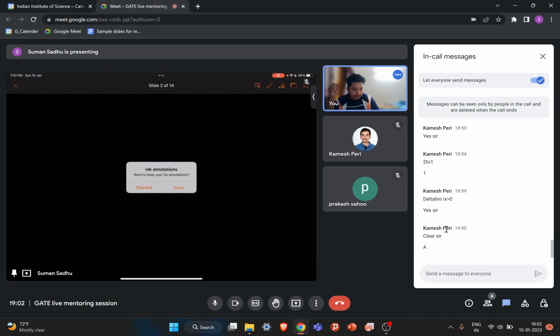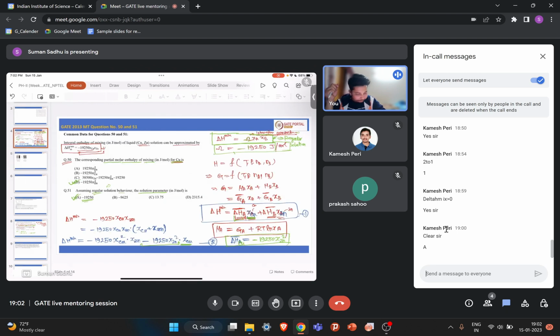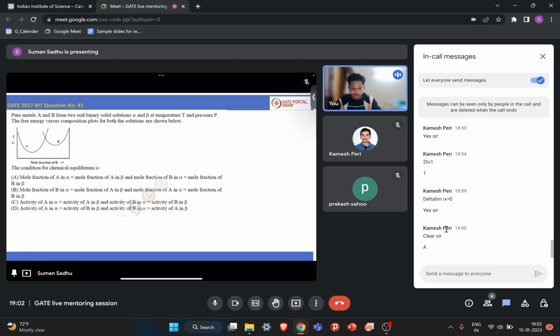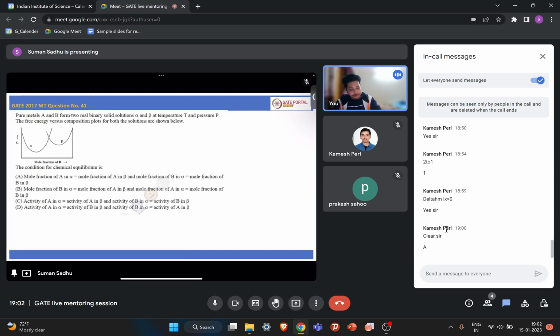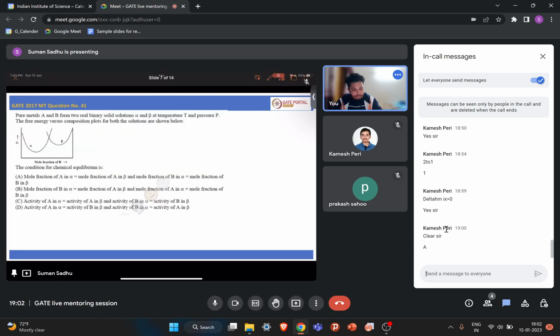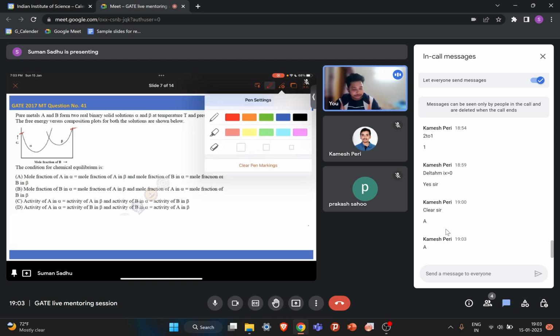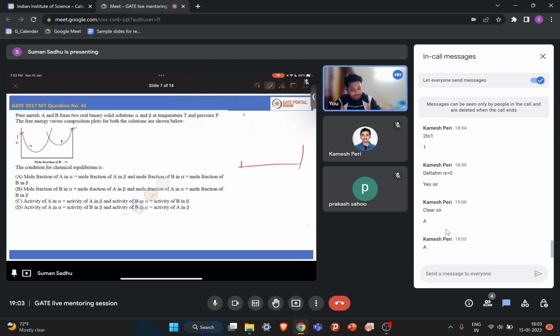Okay. So now let us move to the next question. This we have already solved, right? Now this question. In case of only one element, like one type of crystal structure, you can draw the free energy curve like this. That is a single free energy curve, right? But when one end's crystal structure is different from the other end, then you will have two different free energy curves, not one single free energy curve connecting these two. So that's why here these two free energy curves have been drawn separately. One is for alpha.